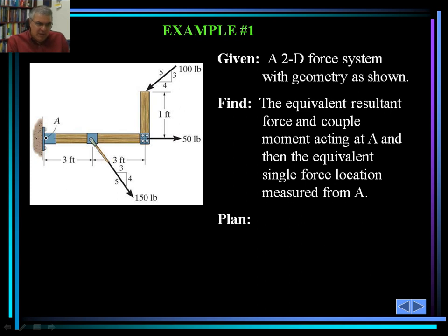We are trying to find an equivalent force. The forces acting on this system are going to result in a moment and also in forces, the reaction of the forces at point A. We would like to see if we can find an equivalent resultant force and a couple moment acting at A, and then the equivalent single force location measured from A. Let's see if that is possible.